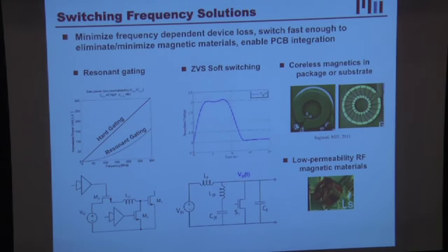First of all, in terms of the switching loss, we'll use zero voltage switched topologies. What that means is we're going to arrange circuit topologies such that I never try to turn on a transistor while it's under voltage. This both reduces that overlap loss that I mentioned and ensures that I don't dissipate the internal capacitance when I turn the device on. So I'll make sure the device voltage is already zero when I turn it on.